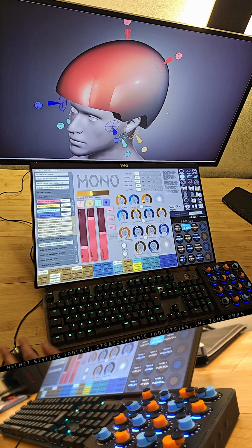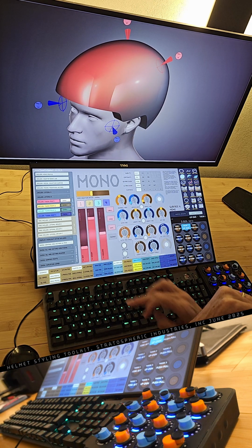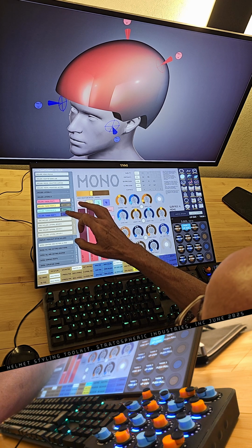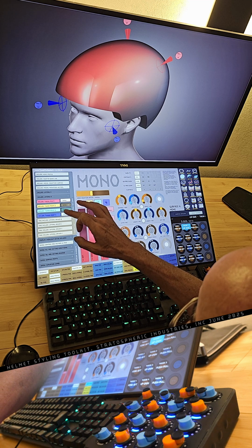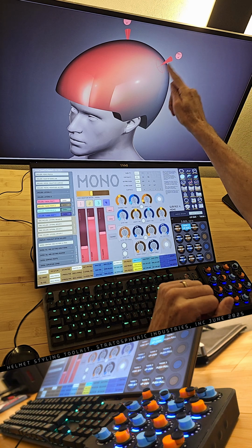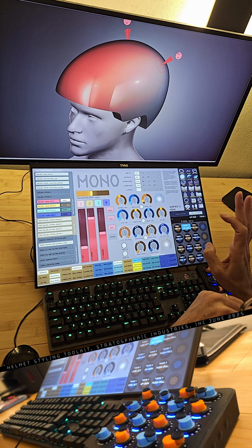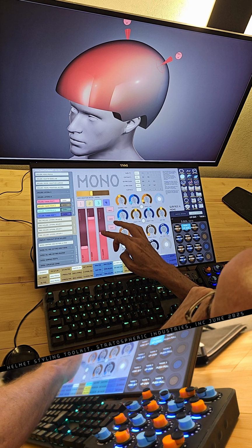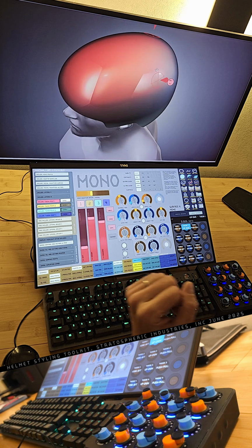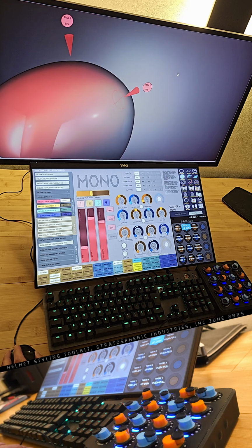Let's turn off the display of the other points just for eliminating the visual clutter. We have point number 1. Sometimes Grasshopper goes a little bit deaf during a solution, so the way is to toggle it back off again. Gone. Okay, now we can increase the magnitude. What this point does is pushes and pulls on this surface. So first we're going to do it without affecting the surface. We are going to move the magnitude outward. We can see the display. The amount registers on the pin. It is now moving 9.5 millimeters away from the surface.